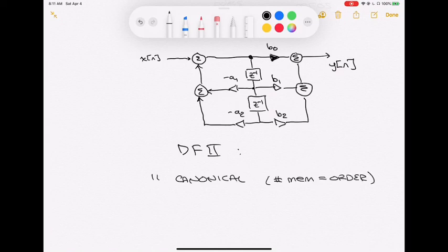That's a good property of this structure. It has, though, poles leading then to zeros. It puts the poles first. Those poles first tend to make things big, and then the zeros would pull them down to their final value, but making things big first gives us an increased chance of overflow, and so that's not such a good thing. We've exchanged a structure that was a sad happy, and we've made it now a happy sad. So it's about a net balance of being equal. We would like to do better.